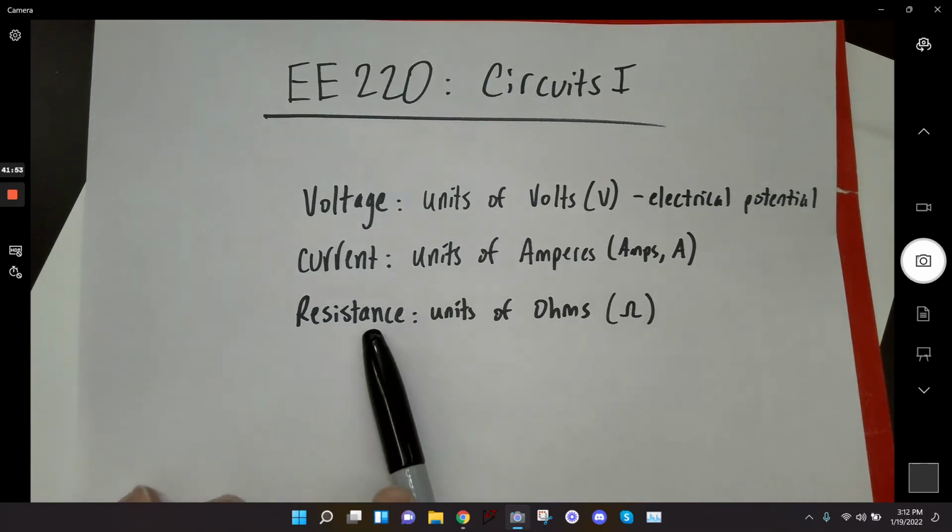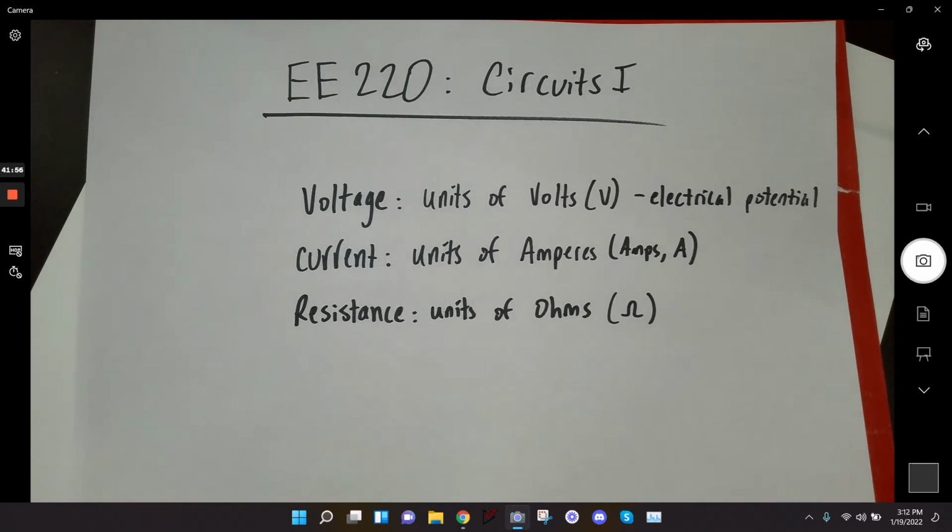What is resistance? It is the amount of resistance, literally, that a device has to current flowing. So larger resistance means that device is resisting the current flow more. You can think of it as a pipe for water. A big wide pipe will not resist the flow of water much, right? Because it's wide open. If you condense that pipe, or you kink a hose, you're adding a huge resistance. The water can't get through the hose like that. That's how resistance works in electrical circuits.